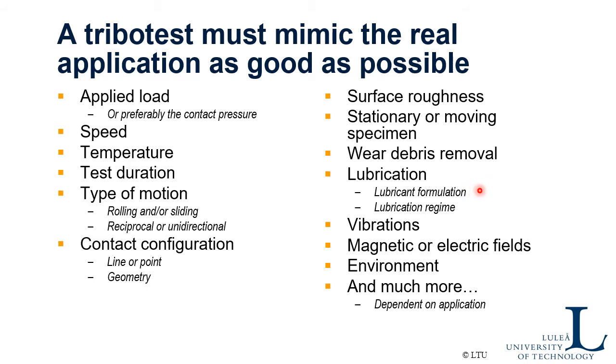How is it lubricated? You must use the same lubrication, same formulation, same regime of lubrication, of course. You can't operate it in boundary lubrication when you know that the real application operates in full film, or vice versa. Are there any vibrations there? Are there fields like magnetic or electric fields?